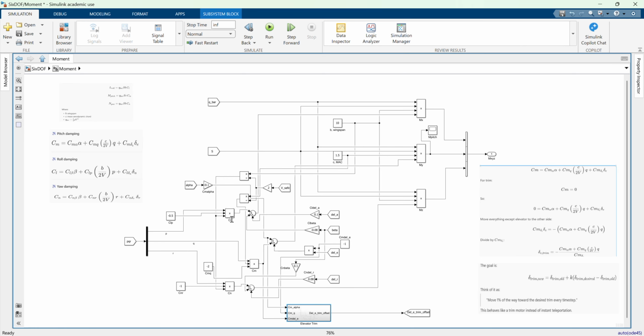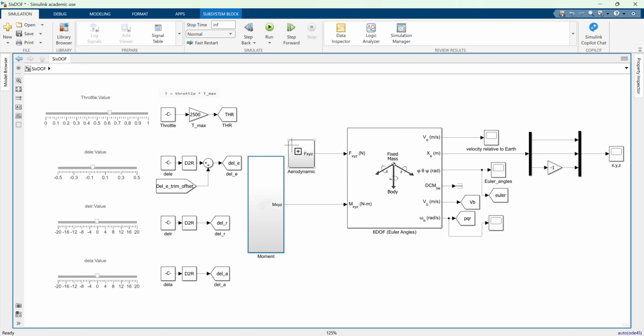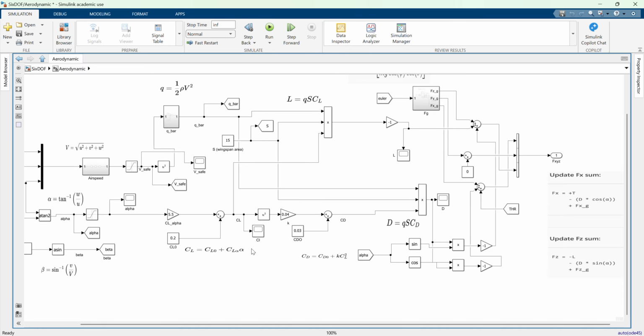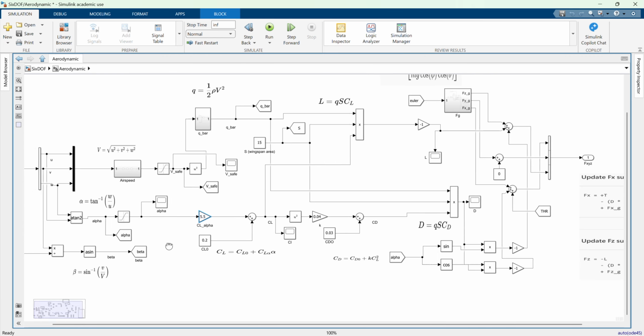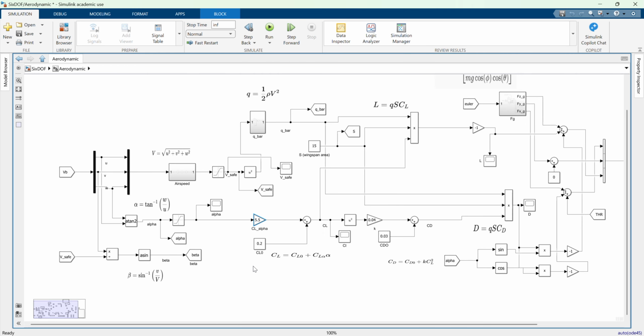You are actually going to use lookup tables for them. And those lookup tables will convert these things into functions of a specific parameter. For example, you know how this CL alpha is a constant now, that will end up becoming a lookup table, which will give you CL as a function of alpha. So that way everything will become a function and lookup tables.